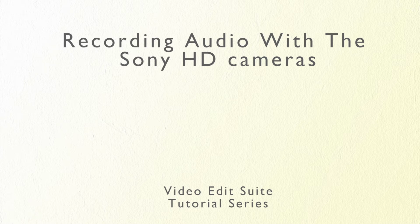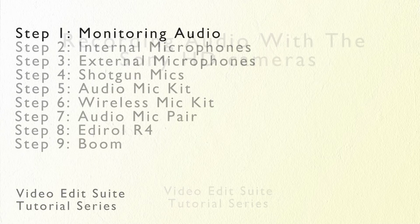In this tutorial you will learn how to use the audio settings on the Sony HD cameras. This includes both internal and external microphones. You can use any XLR mic with these cameras. There are two XLR inputs on the camera and both can provide phantom power.